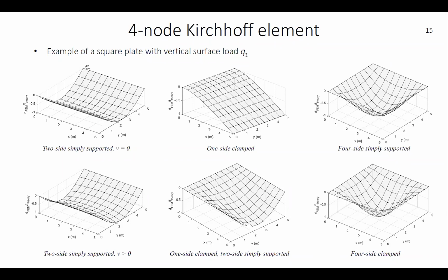So this will act as a beam. You will have the same example in exercise A, and you will see that if you have 0 Poisson's ratio, you will predict the same displacement using simple beam theory. So here is just a ratio of what this model gives compared to the theoretical results.